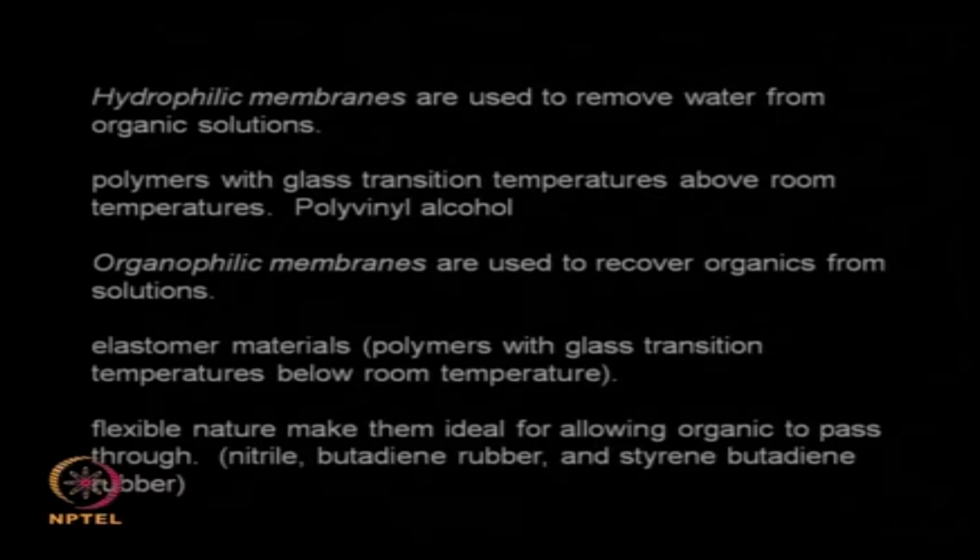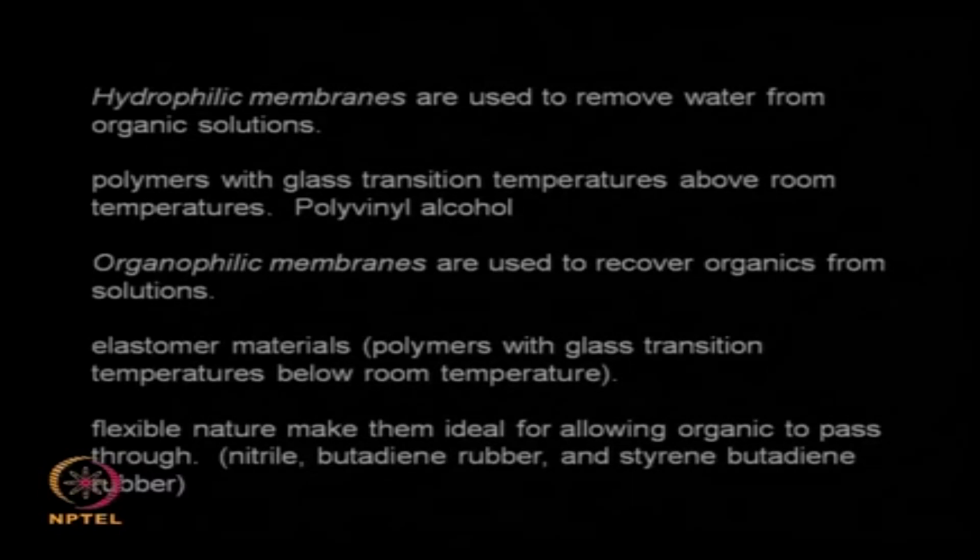Now let us look at membranes. As I said, you have two types of membranes: hydrophilic membranes, and organophilic or lipophilic, or hydrophobic, membranes. Hydrophilic membranes are very good for removing water from organic solutions. That means the amount of water present in a mixture of organic solvent is very little, and I am interested in only removing that water.